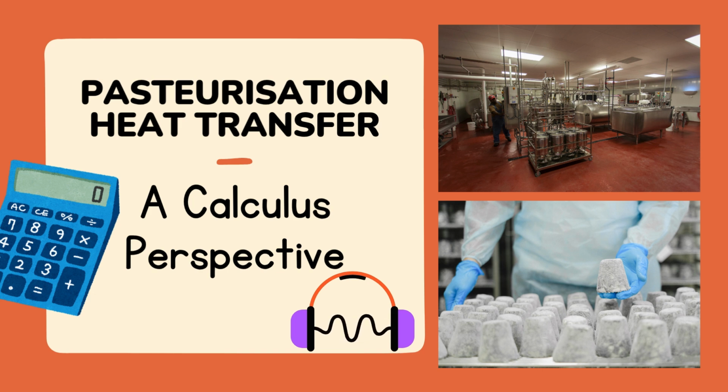And this total energy, this number, is critical. It directly links to what's called the thermal dose, or often in the industry, the F0 value. F0. It basically quantifies how effective the heat treatment was, comparing it to holding the product at a standard high temperature, like 121.1 Celsius, for a certain equivalent time. It's a standard measure of lethality. So the number you get from doing that integral, that F0 value, is what engineers look at to say, yep, this batch is safe.